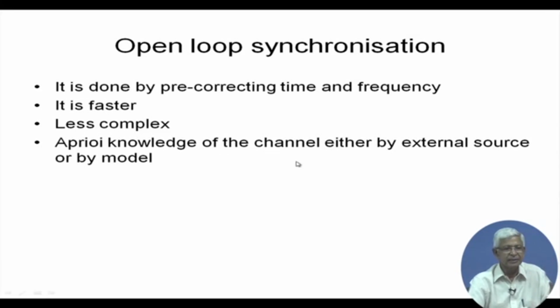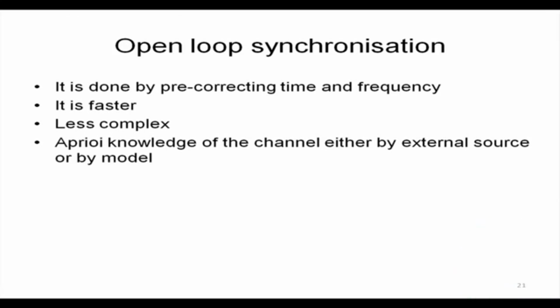Let us say in case of TDMA, if you remember the TDMA lectures, there is a reference station which maintains the network, the frame timing, etc. So, it has complete information of the satellite position, its ephemeris, as well as the location of each of the stations participating.